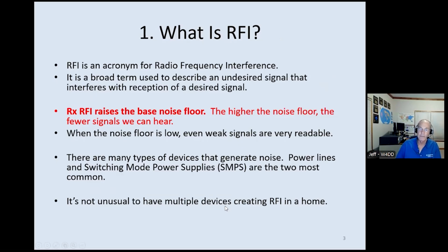So what is RFI? It's an acronym, radio frequency interference. A very broad term used to describe an undesirable signal that interferes with the reception of a desired signal. Why do we dislike it? Well, receive RFI raises the base noise floor, and the higher the noise floor, the fewer signals you're going to hear. So it's in our best interest to increase the signal and decrease the noise to produce a better signal to noise ratio. When the noise floor is low, even weak signals are very readable. There's no problem reading S1 signals as long as the noise is low.